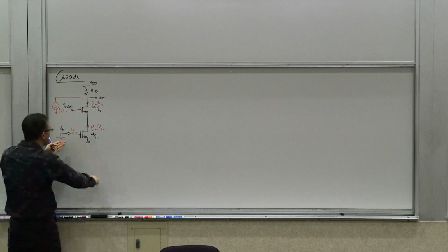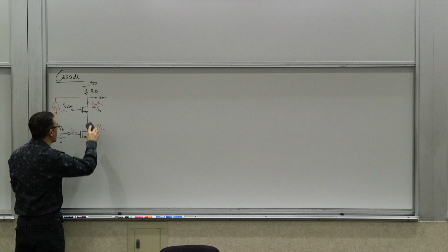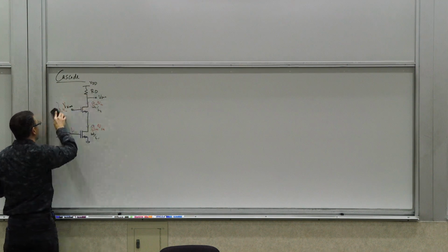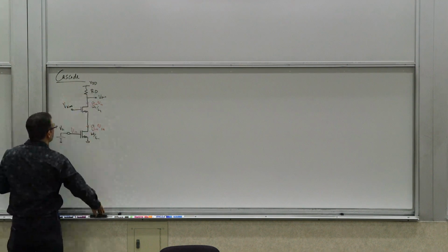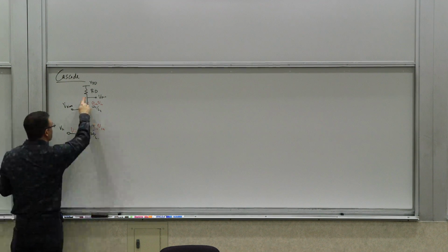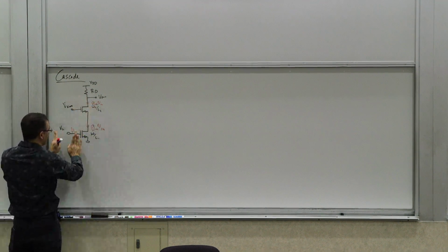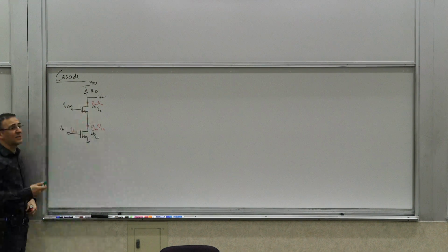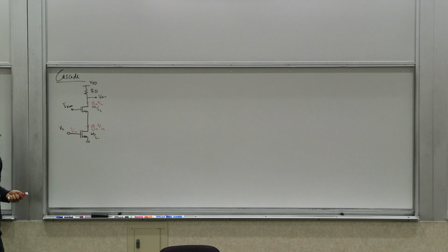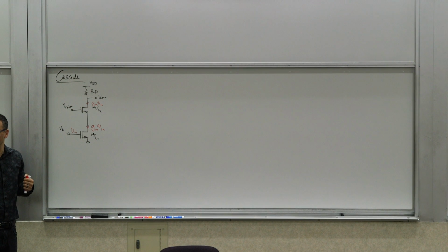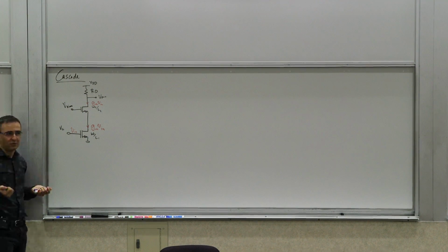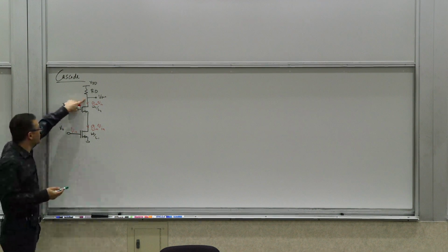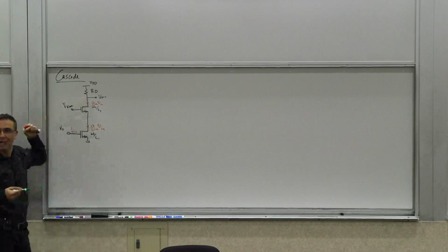So when I draw these pictures, that's what I mean, right? I'm going to erase this now, but you can think about it that way if it bothers you. This red stuff means that there's a current source being pulled out of it, and you can ignore the effect of this guy then, because that would replace this. Now, if I want to know what's the voltage on that node, how do we do that? If I know that there's a current being injected into it or being pulled out of it, what else do I need to know? The resistance, right, to apply Ohm's law. So I need to know the total resistance on this node, because that current source was being pulled out of it.